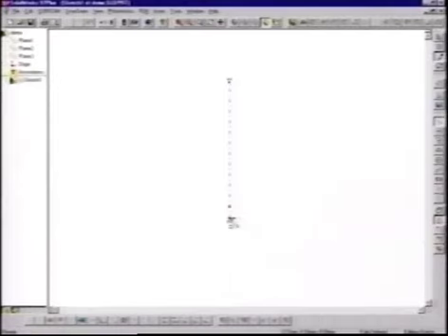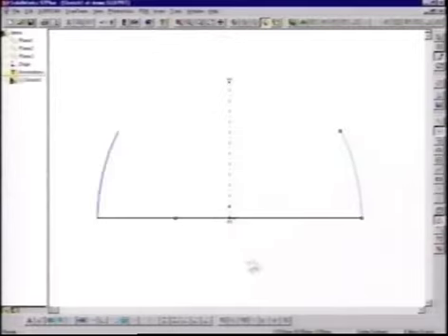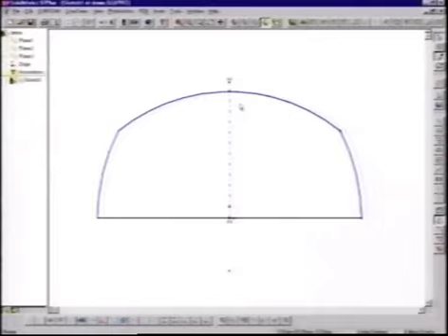Watch as the sketching tool helps Joe create his 2D geometry. In this case, he's sketching with mirroring on. What that means is as he sketches one side, the other side is automatically mirrored or created for him. Watch as it tells him when curves are attached to one another, whether they're at endpoints or on the curves, helping him every step of the way.